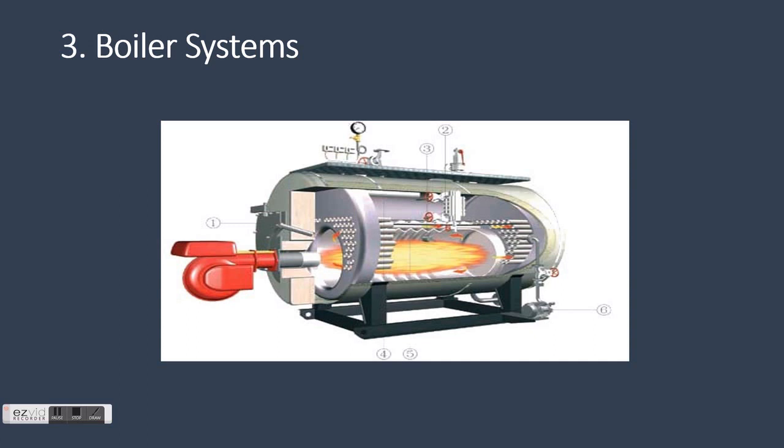The boiler system comprises a feed water system, steam system and fuel system. The feed water system provides water to the boiler and regulates it automatically to meet the steam demand. Various valves provide access for maintenance and repair.